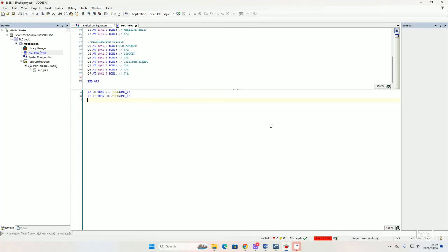We had our sensor, which is I1, that was activating the conveyor belt to start running. And then what opposed the process is I2, which stops the conveyor belt from running once a part is detected by the sensor. So these inputs that are opposing the process, we're also going to insert them in structured text.